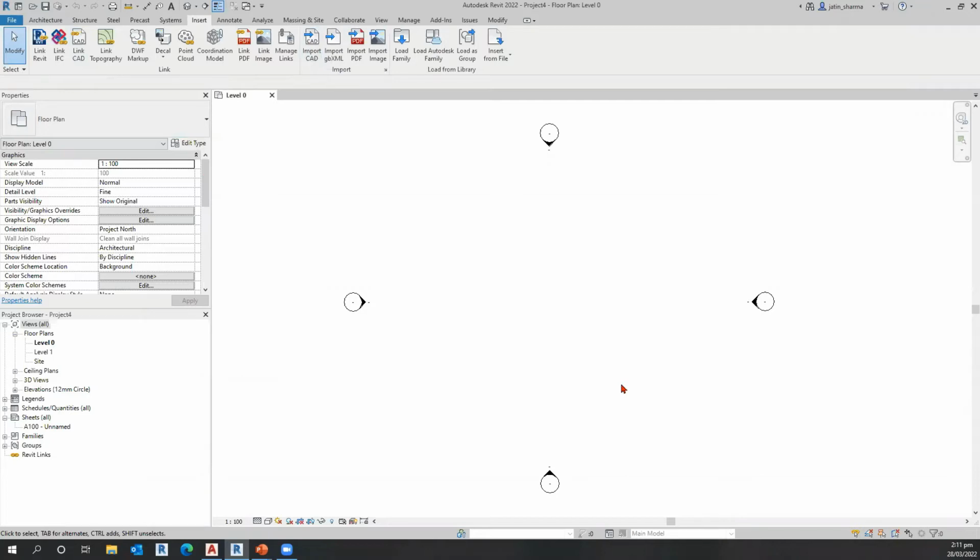The other thing that you can do is that if someone issues a new version of that design, you can just rename that DWG to be the name of the linked file, replace it with the new version in that folder location, and Revit will just automatically connect to it so that you're not having to manually make changes and go back and forth, okay?